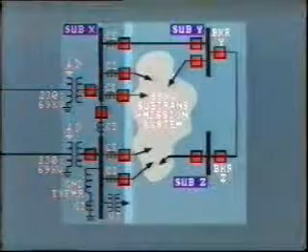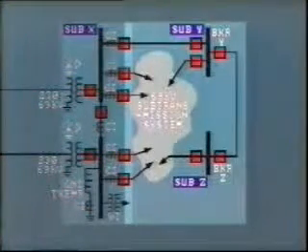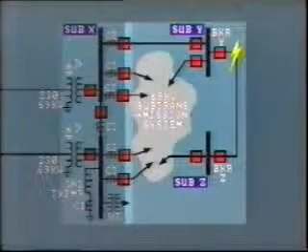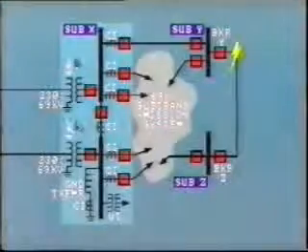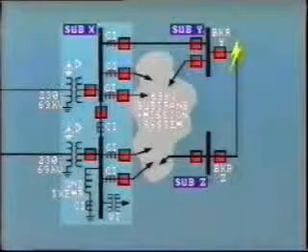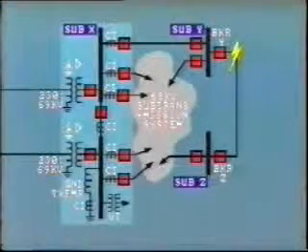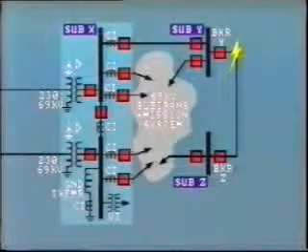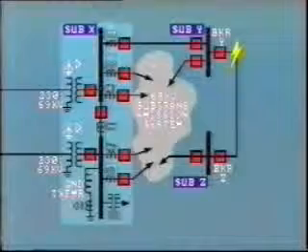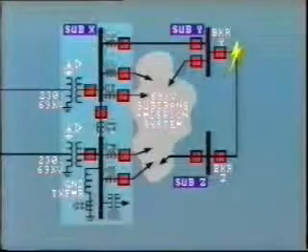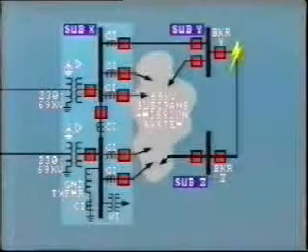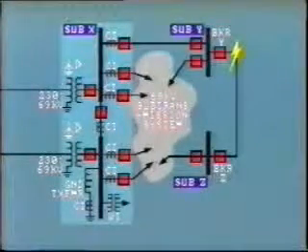Here we have a fairly extensive 69 kV subtransmission system that experiences a fault on the tie line between substations Y and Z. The 69 kV system is delta connected, but effectively grounded through zigzag grounding transformers located at substation X. Notice that all the oscillograph equipment is installed in substation X, remote from the fault location.